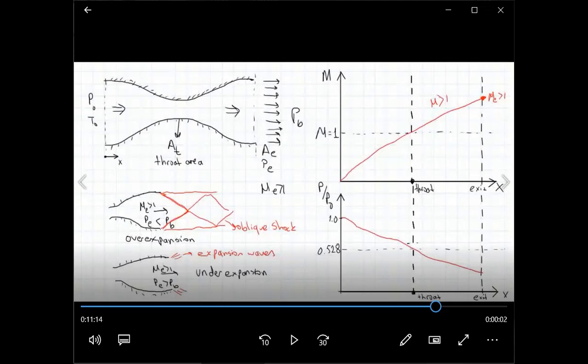So generally, when we are designing propulsion systems, maybe not for space launch applications, because that's not our main concern, that begins and ends in 8 minutes from sea level to space. But during more sustained flight conditions, long range, horizontal flight conditions, we try to design our engines such that we keep exit pressures equal to the atmospheric pressure, at least in the design condition, meaning for whatever altitude we are designing the aircraft for.